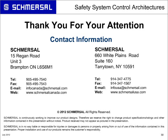What about using one solid-state RFID door switch on a door? Can you achieve a Cat 4? If I understand the question right, one solid-state RFID switch. It's the basic principles of the overall design of the switch. If you're using an RFID switch or a proximity switch, they're not safety switches.